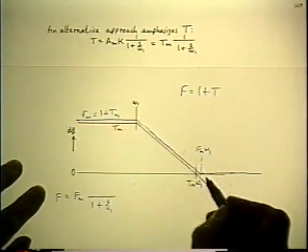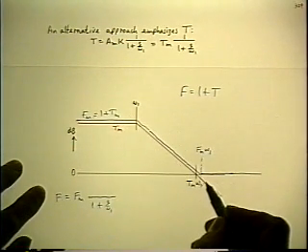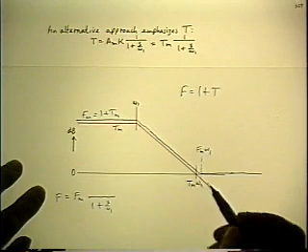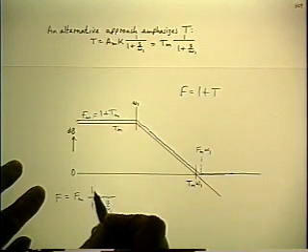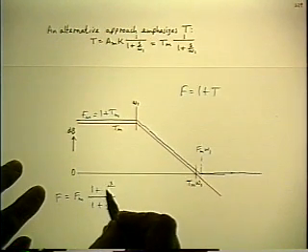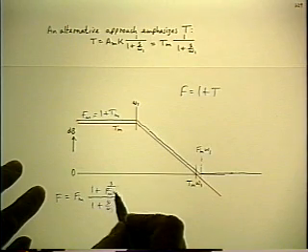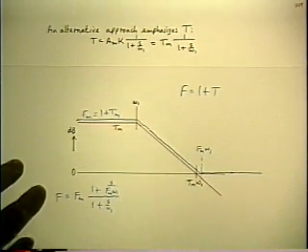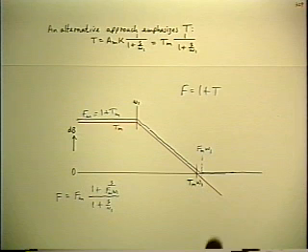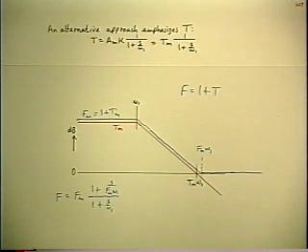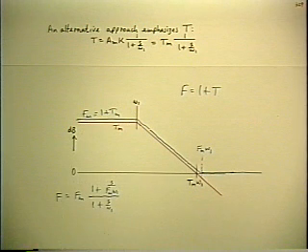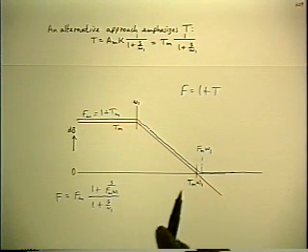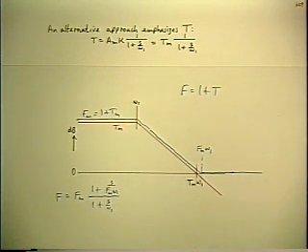You continue to look up, you see a concave upwards corner, so that's a normal 0 at Fm times omega 1. That's the answer, quantitative, for the factored pole zero form for F, which has been derived by a geometric construction with no algebra.